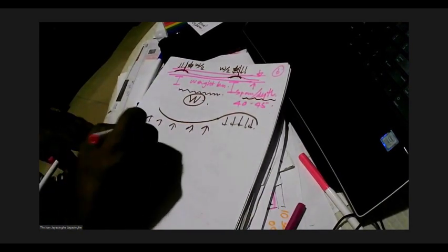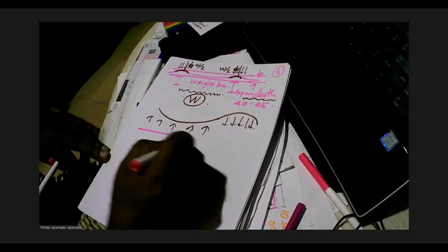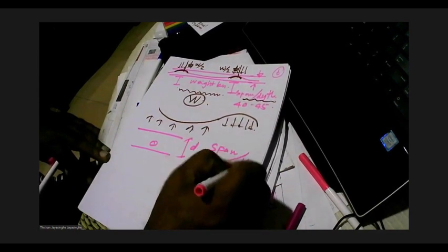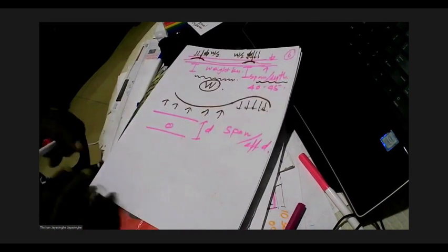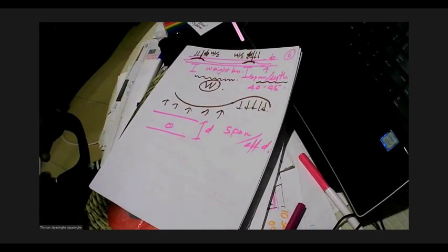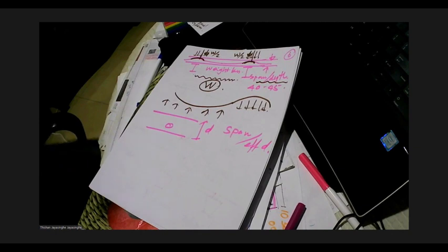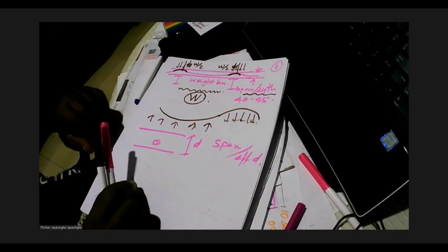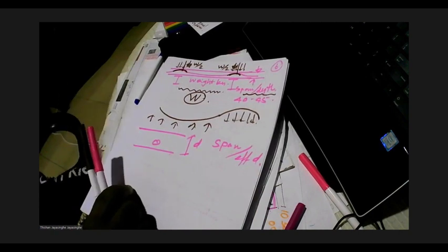Now here, when you have reinforced concrete, we talk about the span over effective depth. But here we are talking about span over depth, because the full section is there. So you can see when we say the ratio is 45, we are actually talking about reasonably thin slabs. I'd like you to appreciate this particular behavior, because we can make use of it later for designing flat slabs.